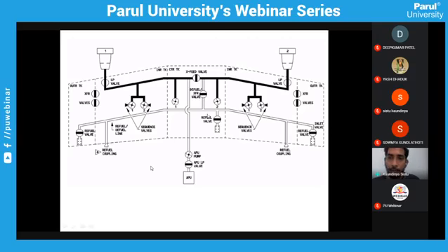Now, after you fuel this line, if you want to pump into engine 1 or 2, you have to use this left wing. You can turn on pump 1 or 2. For example, I am turning on pump number 1 or 2. Nothing will happen. From here, follow my mouse: the fuel flows from here to here and here. It will go in 2 directions, spreading till here and till here.